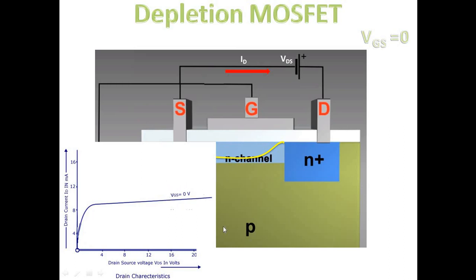So now let us just think about a major striking difference that we have in case of these devices, which is different from whatever we discussed in JFET. So here one interesting part is that in case of JFET we saw that this saturated current that we had here, IDSS, was the maximum current that can flow in a JFET. We have mentioned and emphasized several times that IDSS, the current flowing through the device when VGS is equal to 0 volt, is the maximum current that can flow in this particular device, right?